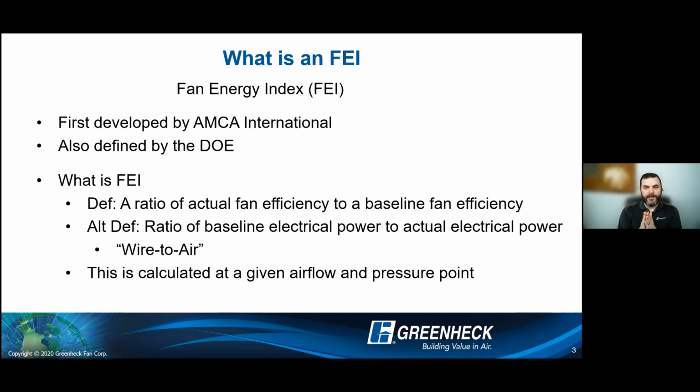So there's two methods here we can look at. I can look at the fan you are selecting compared to a baseline fan and say, okay, this is where you're at. More common route to take is the wire-to-air method or shaft-to-air method. And this is literally looking at how much power am I consuming versus what am I getting out of the fan.